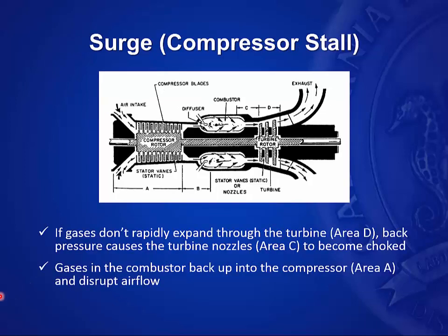Compressor stall is when you have a reduction in the mass flow rate going through the compressor. And anything that will disturb that flow being constant can induce compressor stall. The compressor is supplying air into the combustion section. So if for any reason the mass flow rate suddenly decreases going into the combustor, that will affect the temperatures in the combustor dramatically.